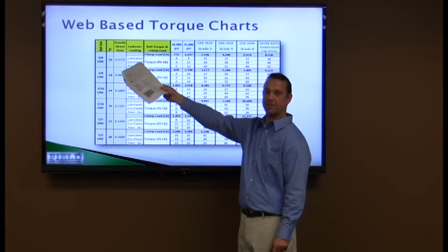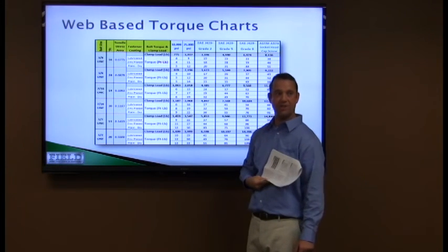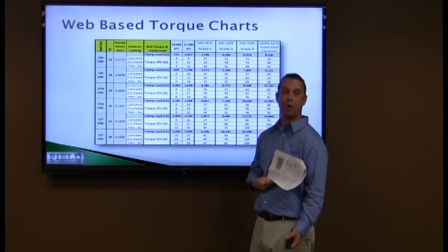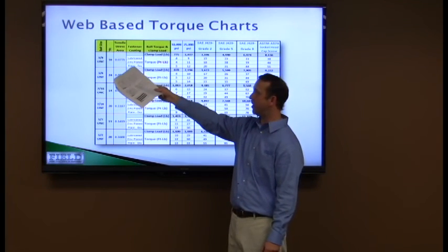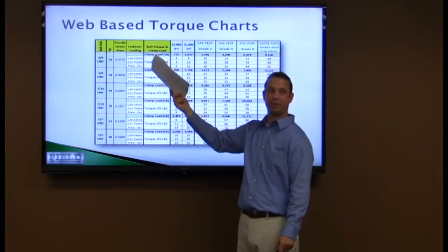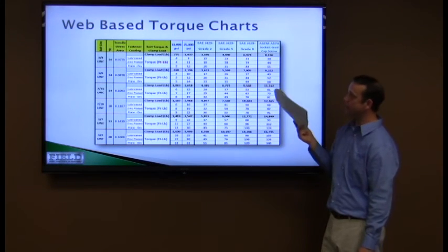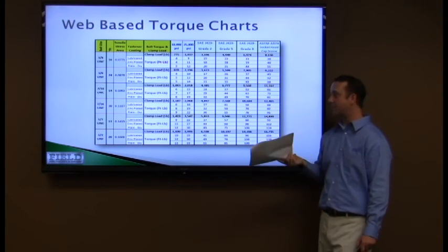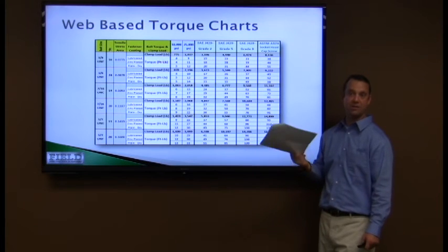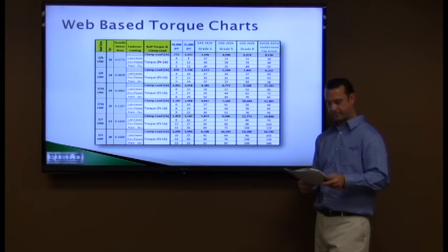These are also not very specific. Again, like I said, different platings give you different coefficients of friction or torque coefficients. Zinc plating might be common, but there are obviously many applications that don't use zinc plating. So again, it's a better chart. There's a lot of information on here. In some cases, this might be good enough. In many cases, you want something more accurate.